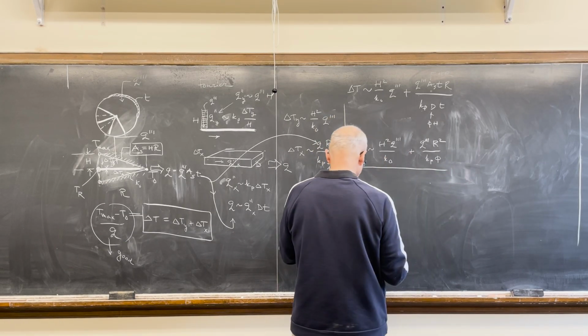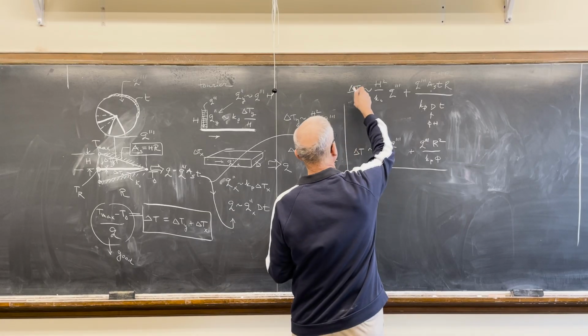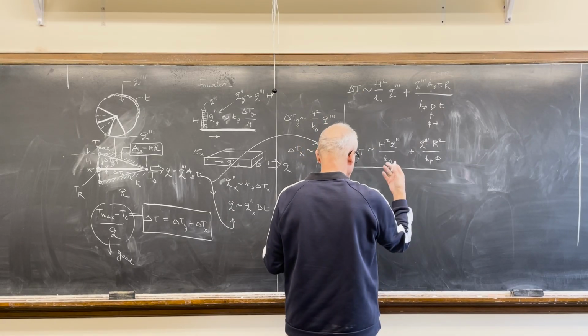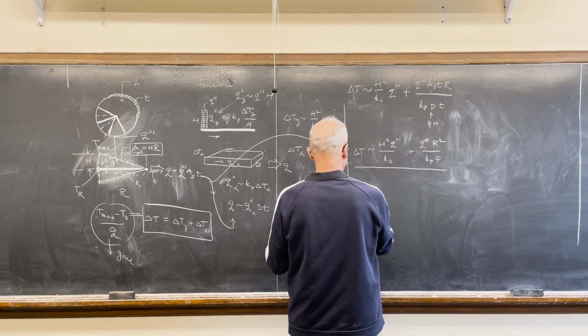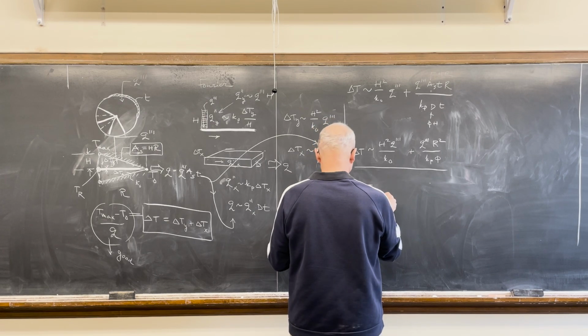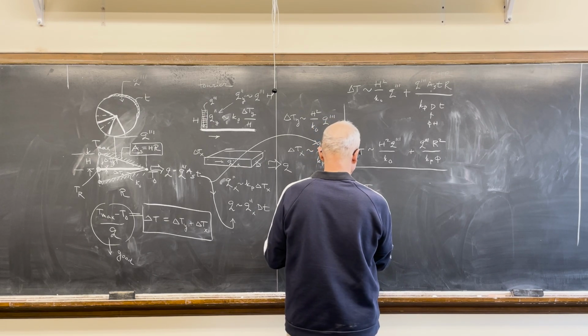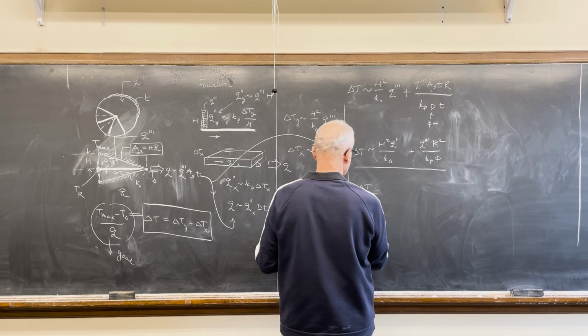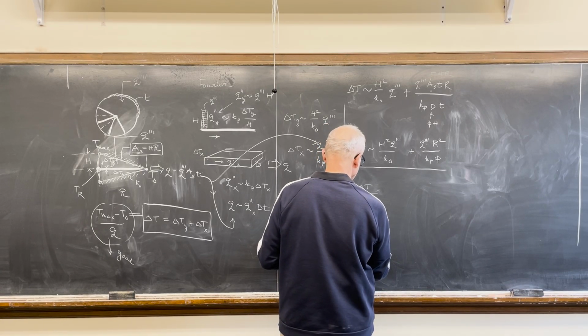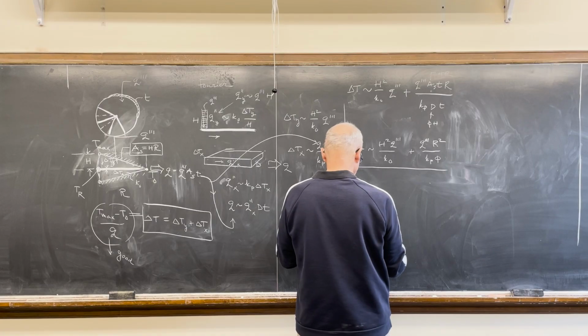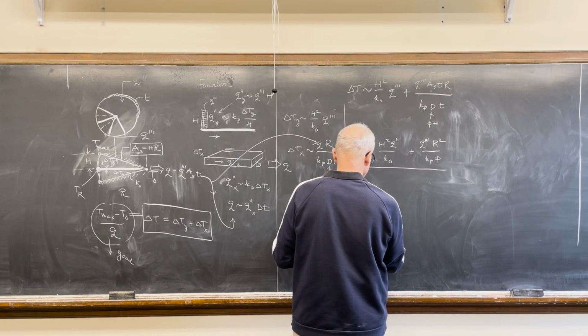And then you non-dimensionalize this so-called delta T as a thermal resistance this way, delta T over Q triple prime A sub S, which would be the total Q per unit length, and then slash K0.